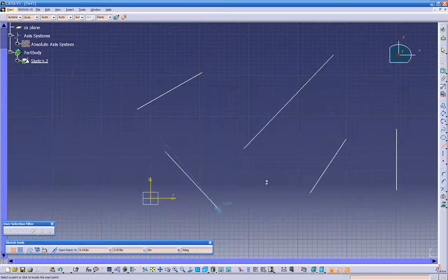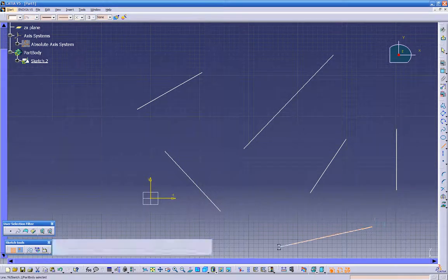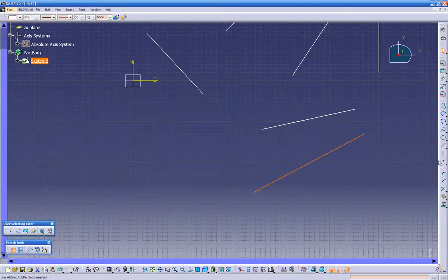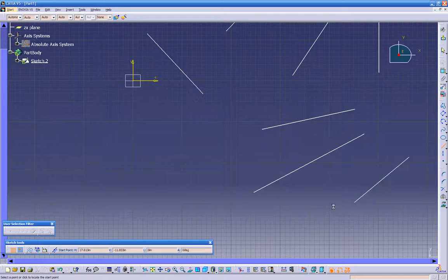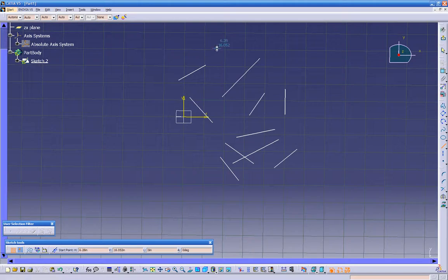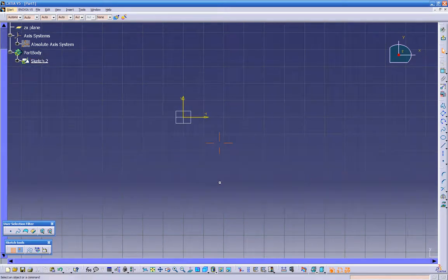So we can keep creating the lines. That way we don't have to go every time, click each line individually. See, right now I'm doing only once. See, it deactivates. So if you double click, you keep on creating lines, which is very handy. So right now let's delete all these lines right here. Click escape, delete, delete, delete. Normal to the view again.